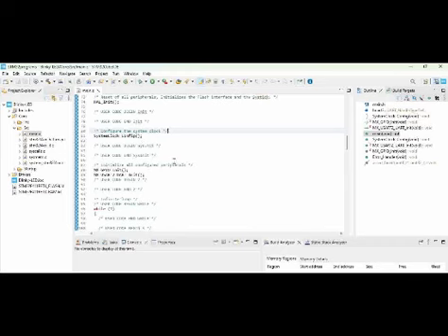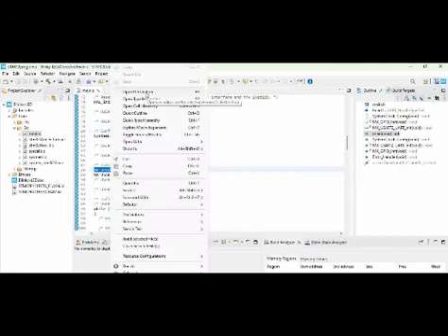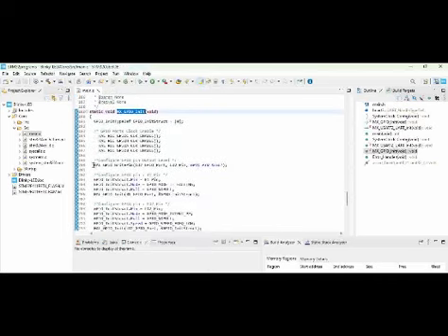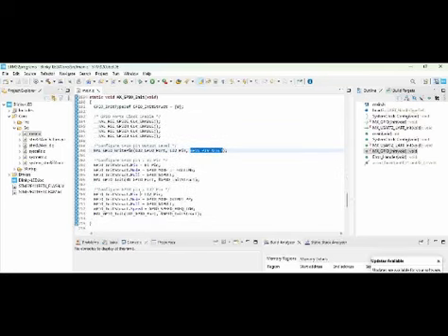But what we did there was a GPIO initialization, which is PA5. When we go here and choose go to declaration, you can see the default state of the LD2 pin is written to reset, that means 0. We also have the LD2 pin configured to push pull, no pull up or pull down, low frequency. So the entire configuration is very clear.